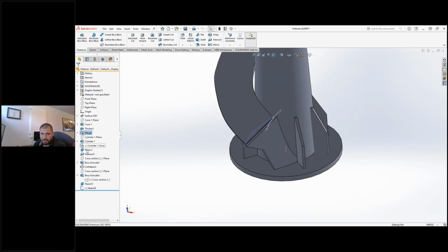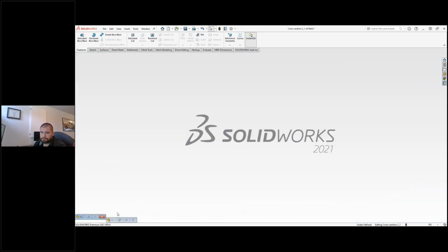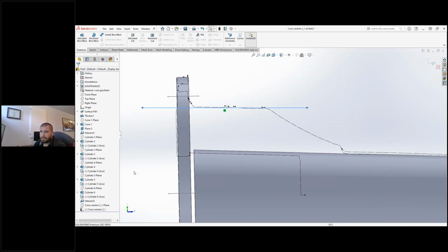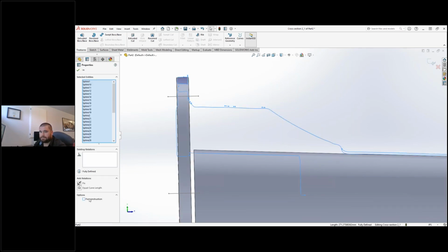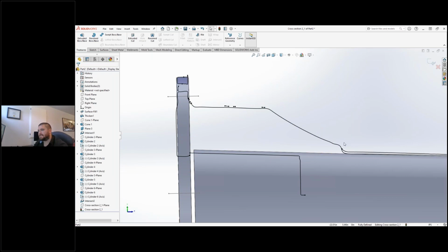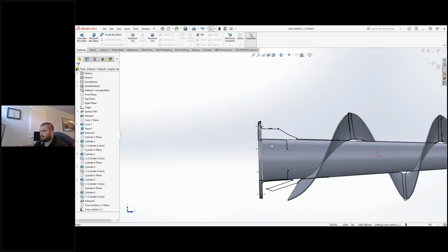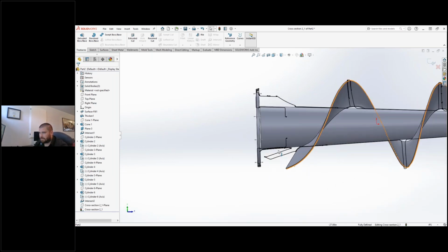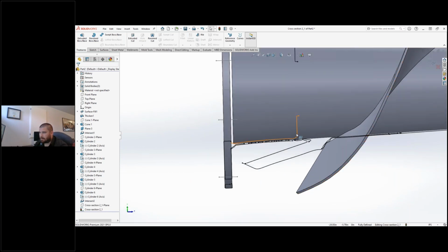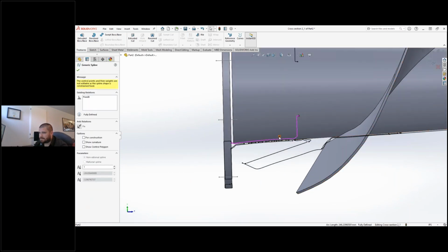Forgot how that one's called. Maybe I can try to show you, or maybe in my other part. So if I go back to the sketch here and delete, let's say, the line I created, and then undo the for construction, you can see that my sketch is black, meaning it's fully constrained, but it's only fully constrained because there's an anchor on the lines. Oh, yeah. You can see fixed here.